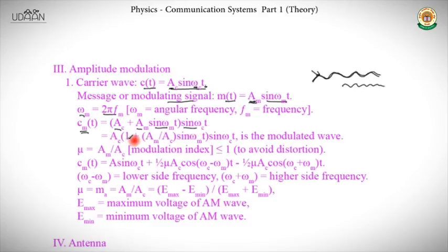Note that this is not just a superposition of two waves. It is modulation. You're adding to the amplitude, and then there is another sin(omega_c t) term. This will give us the total amplitude, and sin(omega_c t) is again the carrier wave frequency and time. So this will give us the final wave. After simplifications, these are just different forms. This equation can also be written as this, and this is known as the final modulated wave.